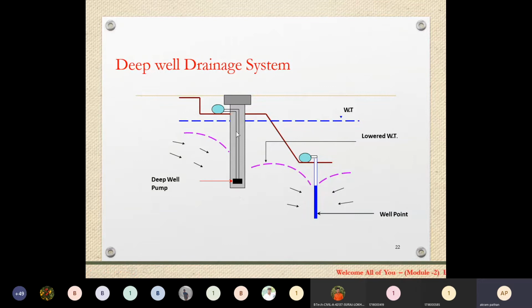So we can excavate the hole below the ground level, and then we have to immerse the submersible pump, as we have in case of our building bore motors. Such a borehole system we have to follow in the dewatering process. This is the submersible pump.